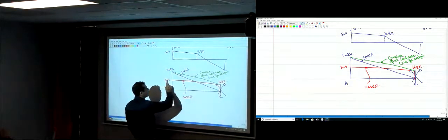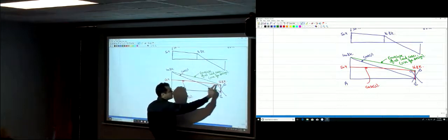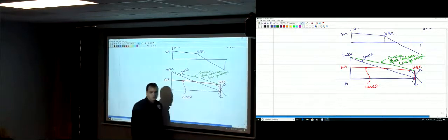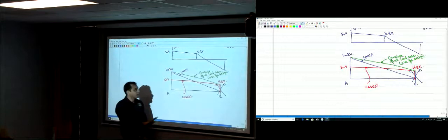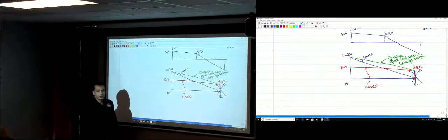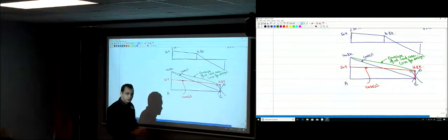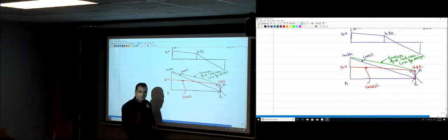The shear here is not maximum. The maximum was 108. This is just 50.4. But now the shear is right in the middle. It's the maximum value that you can get just by applying the live load on that half. So it's 16.8 right in the middle. To maximize the shear force at different points, you would apply the live load on different lengths.